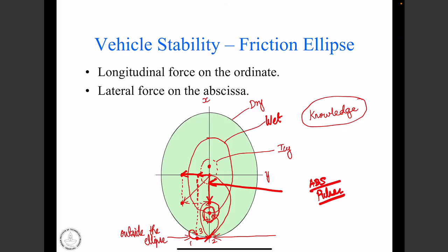So, sir, the friction ellipse, this force is on lateral and longitudinal. This ellipse size also depends on the rate of application of inputs. This ellipse depends on the tire design, and the vehicle level design. This is given once you essentially choose a particular tire design for a particular vehicle.